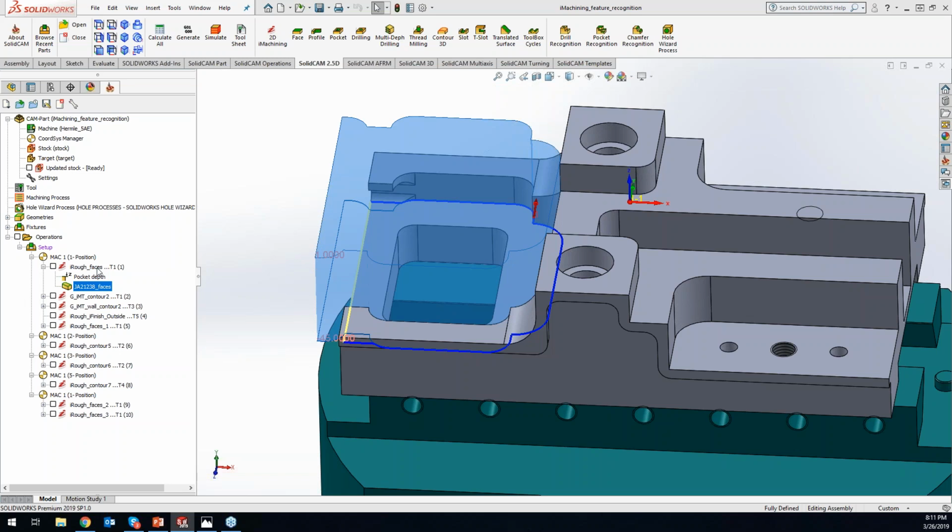And it'll say this geometry is being used by another operation. Please exit operation and modify geometry outside there. That's what it's saying right here: if I want to modify my faces, but I'm using that exact same face definition in another operation, I can right click from right here and actually edit it as well.